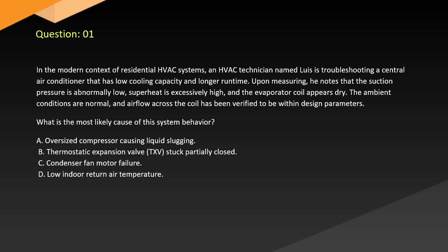System behavior: A. Oversized compressor causing liquid slugging. B. Thermostatic expansion valve TXV stuck partially closed. C. Condenser fan motor failure. D. Low indoor return air temperature.